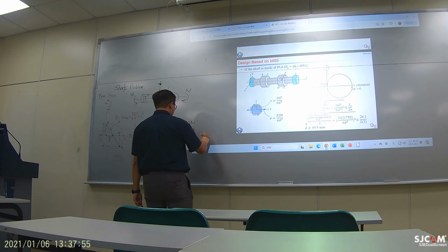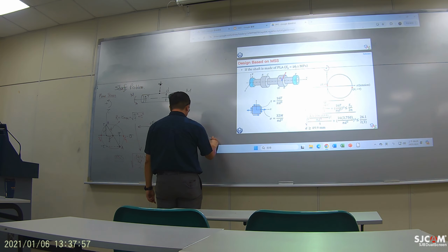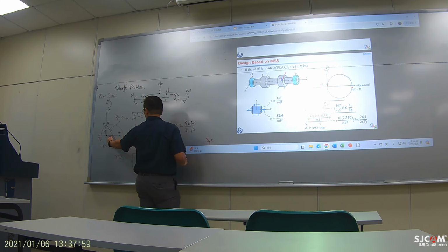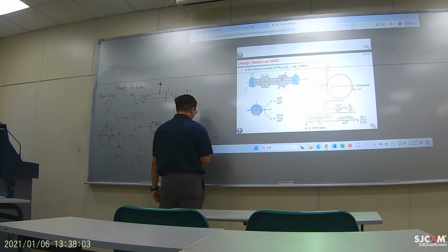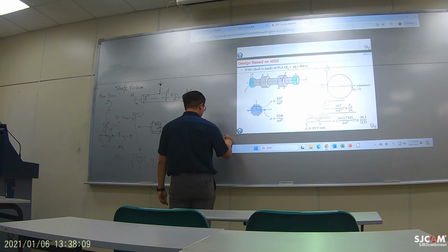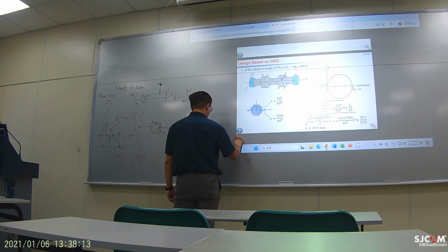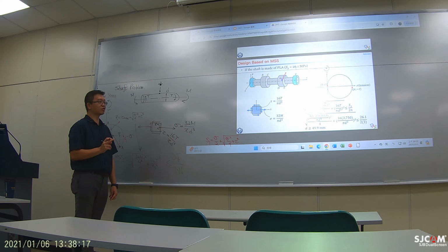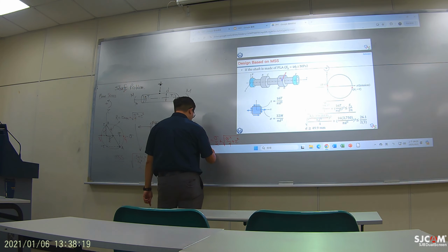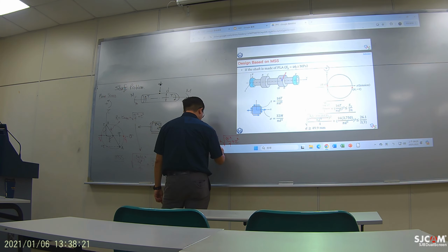So right there, S1 equals the center point, basically half of the stress, plus the radius. The radius is basically this. Right? This is the first principal stress. And the second principal stress is this, minus the radius.